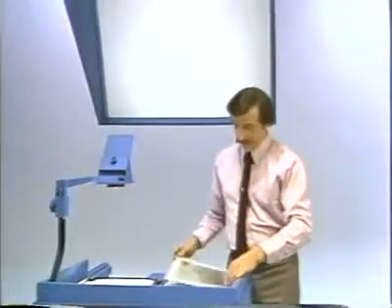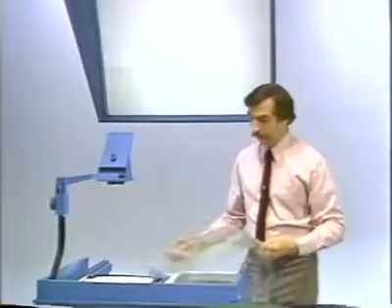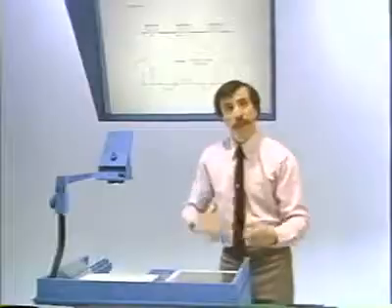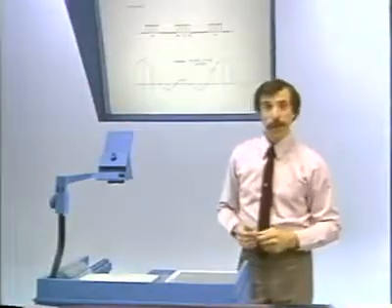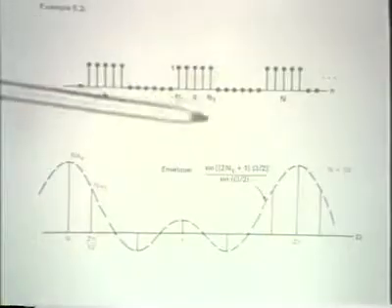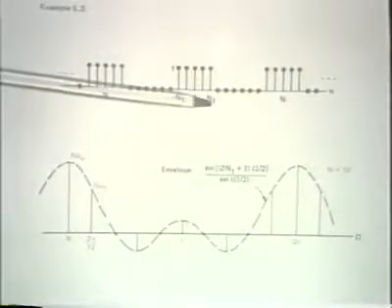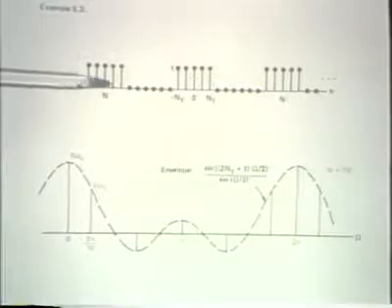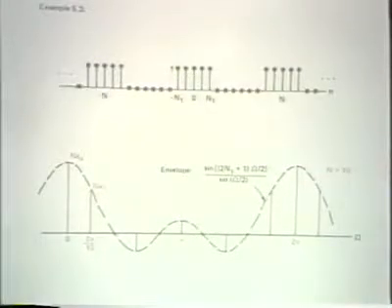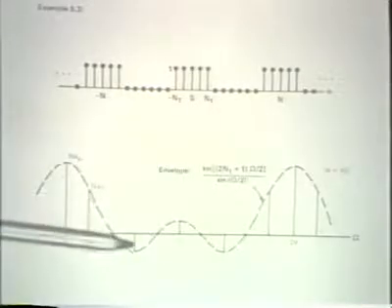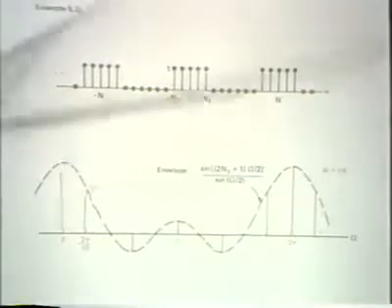Again, to return to the example we have been working through in this lecture, the periodic square wave: if we have an aperiodic signal, which is a rectangle, and we construct a periodic signal, and now consider letting this period increase to infinity, we would first have this set of samples of the envelope.